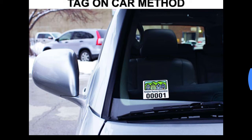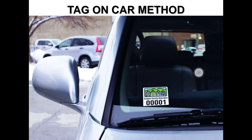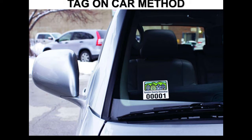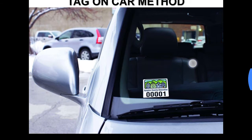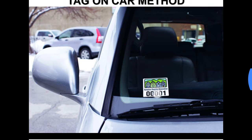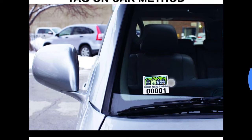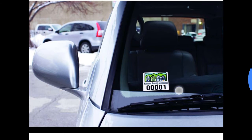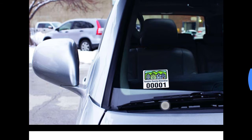Next method is tag on car method. In this method, whenever a vehicle enters our study area, there are surveyors who are placed at the cordon line, and whenever the car enters, a tag which would have different colors and some numbering is attached to the windshields of the cars.